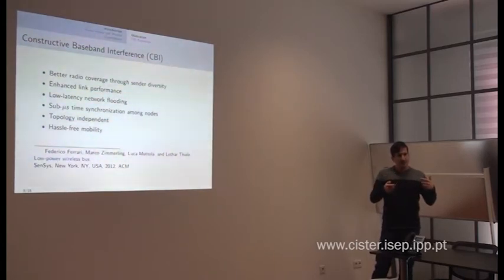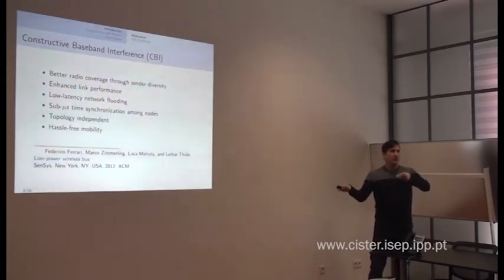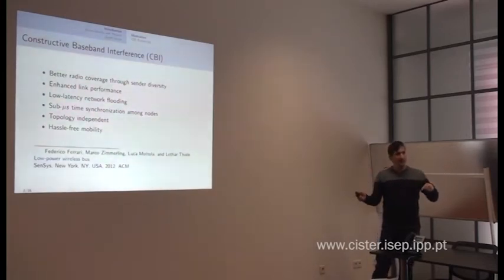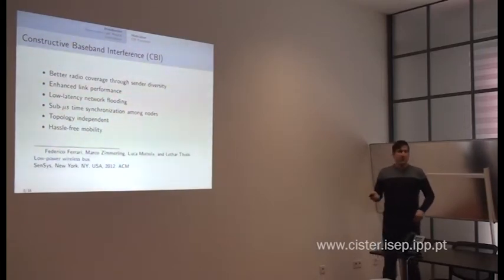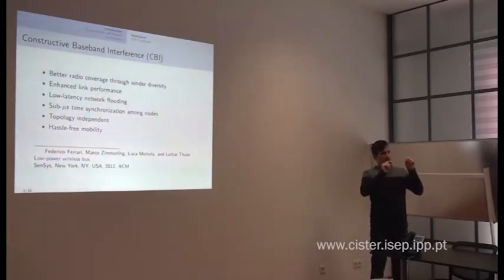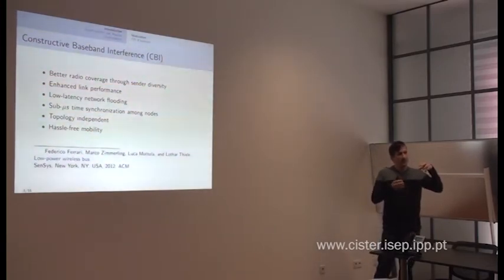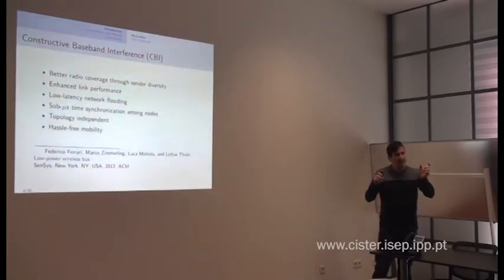So it is counterintuitive, because if the objective of a low power wireless network is to have energy efficiency, and then you make every node transmit what every other packet says at any given time, it seems like this is going to be a waste of energy. But what happens instead is that because they managed to synchronize, the most power-hungry component in the sensor node is the radio. So if you have very accurate time synchronization and you manage to wake up the radio right at the time that is needed to transmit or receive, and then go back to sleep,